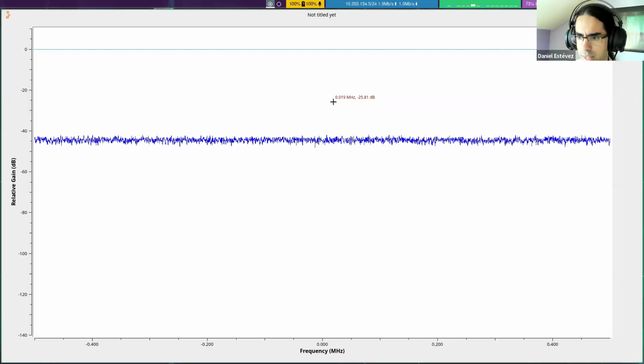This looks pretty much like the noise we saw on the RTL-SDR receiver, especially if there is nothing connected to the antenna. And that is because this is Gaussian noise, which is the noise we typically find in radio frequency. And also something else we can observe is that this is flat on the spectrum. So there is the same noise power on all the frequencies that we are simulating. And the term we use to denote that is white. White means that it is spectrally flat.